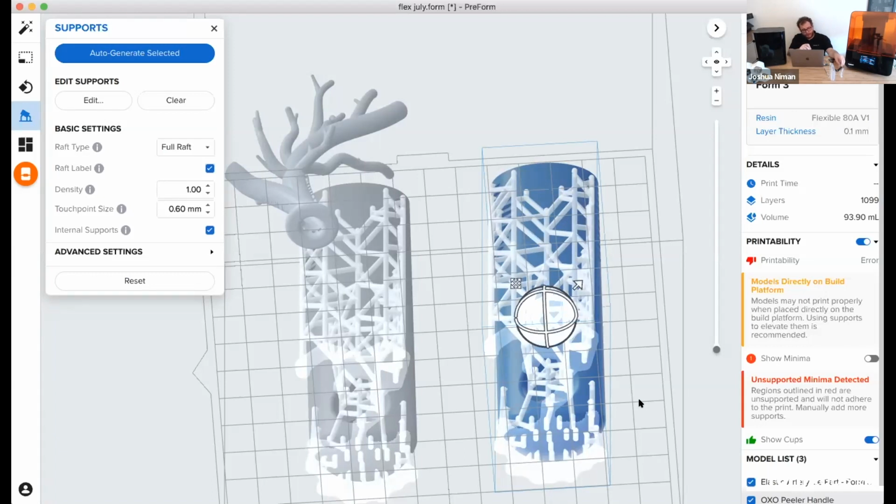The machine looks at the part and it's a lot smarter than you or I, and it can place all its supports at one time. And it decides where they're all going to go relative to each other. And the density tool is how you control that spacing, right? So the location of the supports is not necessarily based on what's best, and it's certainly not based on what's best for a version of it where you remove half those supports or a third of those supports.